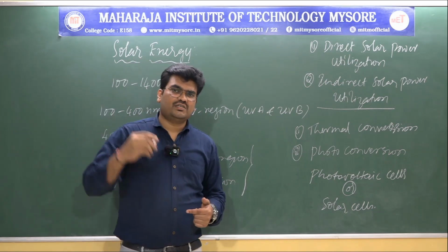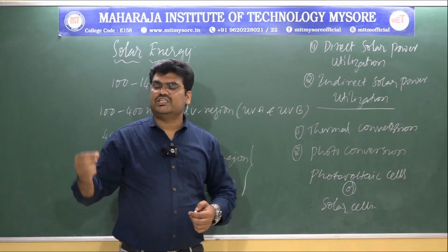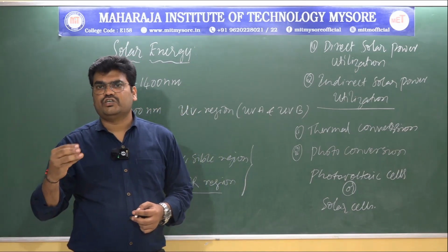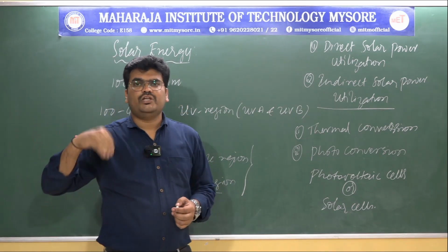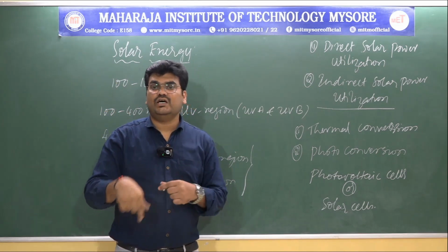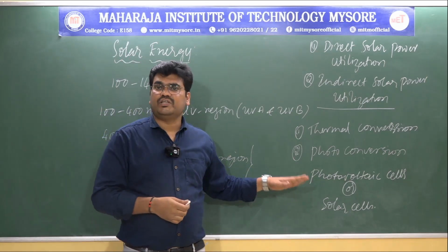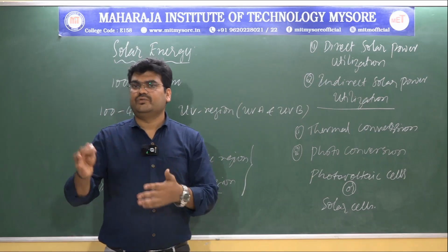So in case of intrinsic semiconductor, the conductivity of the semiconductor can be increased just by heating, right? If you increase the temperature, bonds will break and electrons will jump from the valence band to the conduction band. However many electrons jump from the valence band to the conduction band, that many holes are created in the valence band. So if the conductivity can be increased by increasing the temperature, then they are called intrinsic semiconductors. They are the pure form of semiconductors.